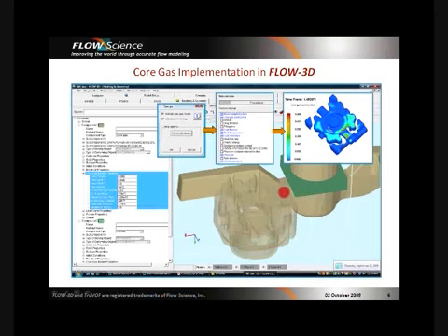Shown here are the components of a casting process where we are studying core gas. The core gas properties are entered over on the left tree structure here. So properties such as the core gas porosity, the core gas density, binder weight, and the composition, the gas properties, etc. can be set. Another great feature is to have selected output data.